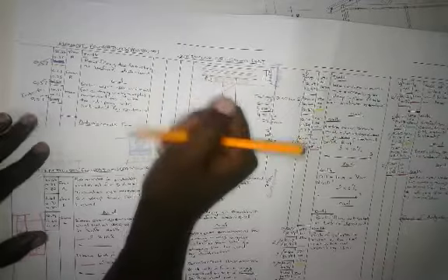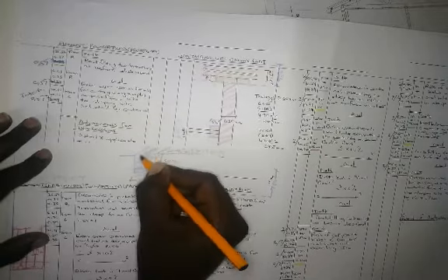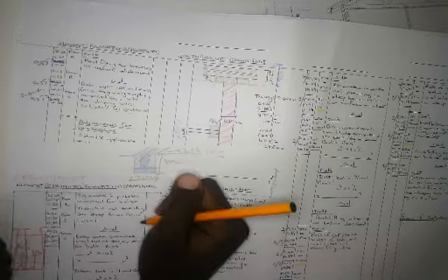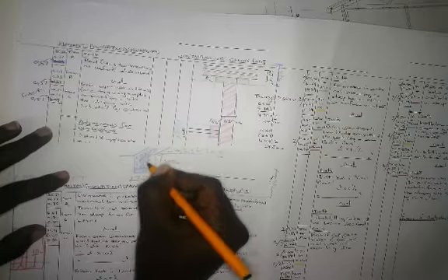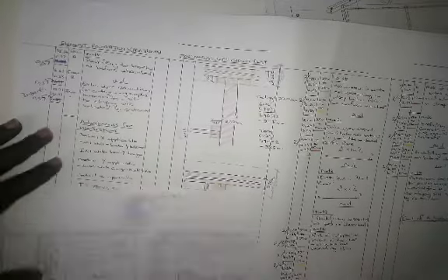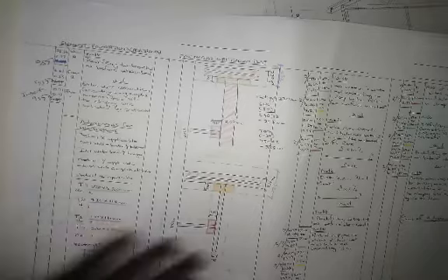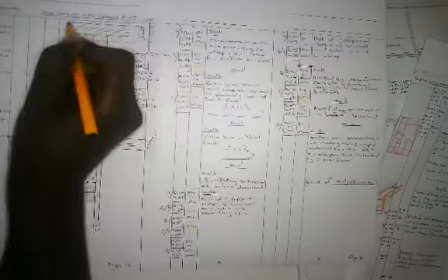So what we are doing is deducting the wall. Remember we had said backfill. Now we have built a wall here, so let's take away the soil that occupies the space for the wall. So deduct backfilling to trenches as before, and extra over for cutting away. The soil that is left over here is the soil for backfilling, and the soil that occupied the space for the footing and for the wall is going to cutaway. But that will be done by whoever compiles the bill of quantities.